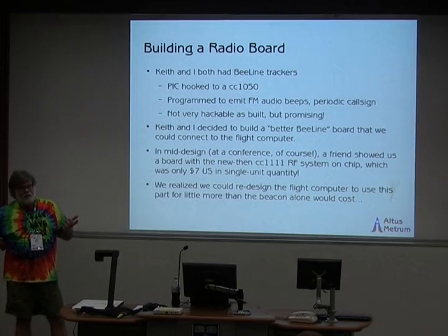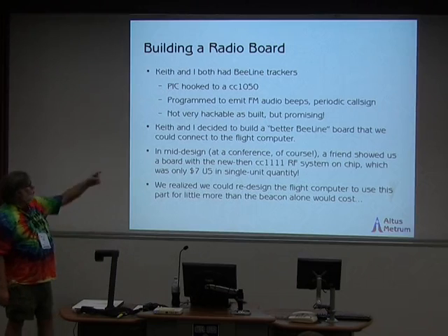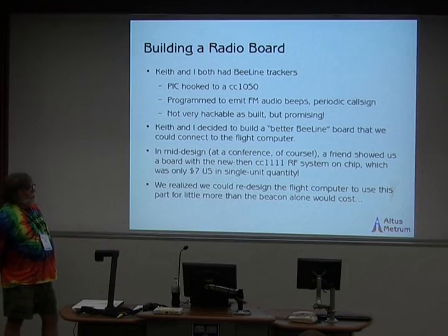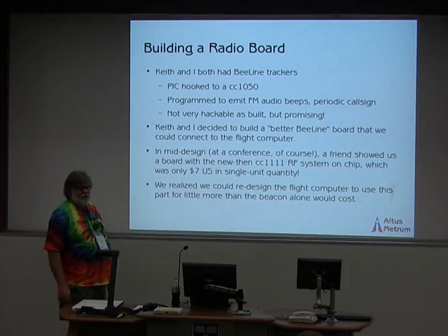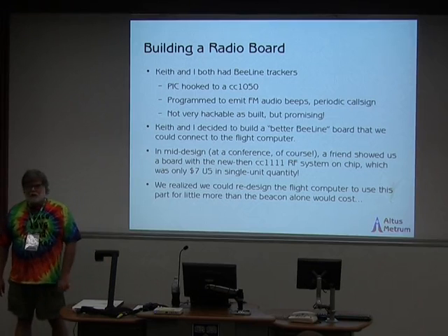So if you had a 70 centimeter HT with a little Yagi, you could use this for radio direction finding. It would occasionally put out the call sign to meet amateur radio regulatory requirements. But it wasn't very hackable as it was built. What I mean by that is there were extra pins on the PIC that you could have used to provide some serial data in from the flight computer, but they weren't brought out to anything that you could easily attach to.